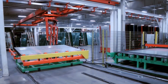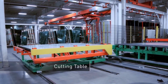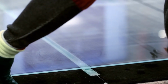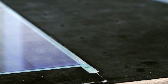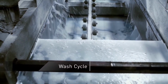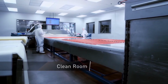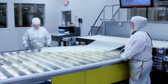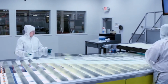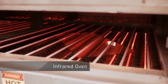The next process is making laminated glass. First, the glass moves to the cutting table, and the sheets continue to the breakout area, where the glass is bumped and separated into individual pieces. And we wash it, and then it comes into the clean room. The interlayer is placed on one of the panes of glass, the other pane is fitted on top of the interlayer, and it passes through an infrared oven.